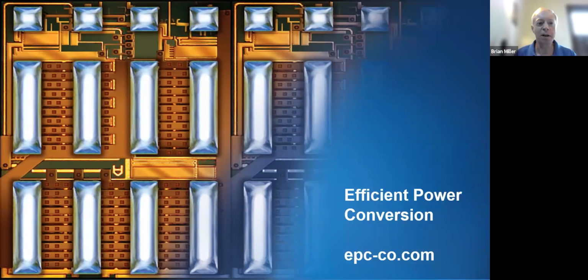In other words, no transient on the drain can induce a spike on the gate to make it go above the threshold to turn on. That's a real nice feature that was added years and years ago on the EPC GaN FETs. It's one less thing to worry about. So the Miller ratio is under control there.